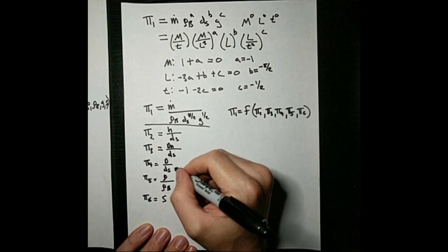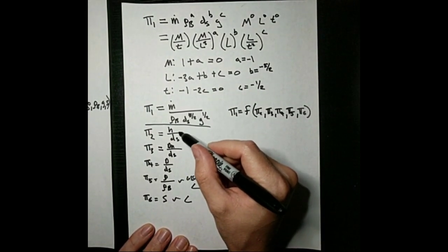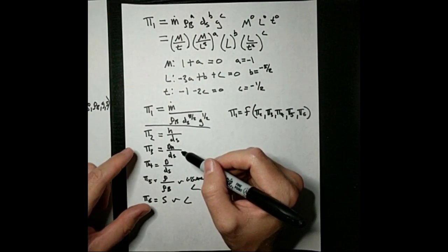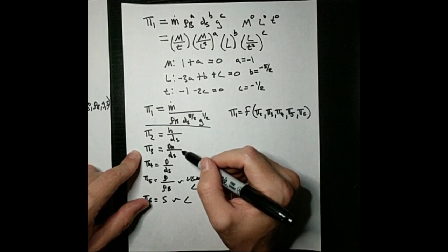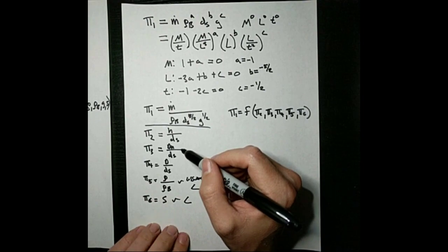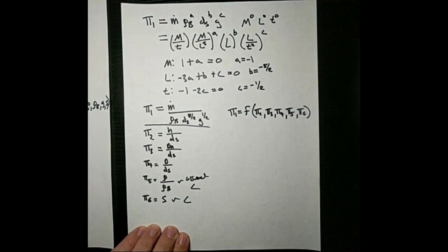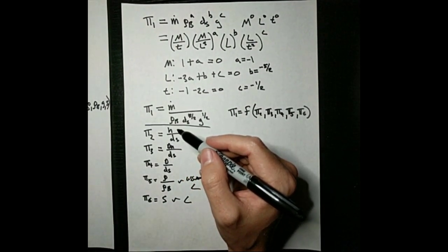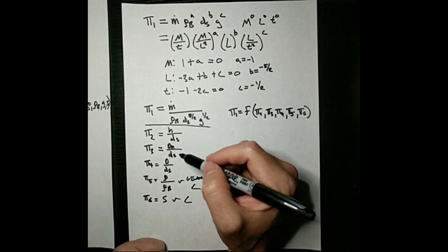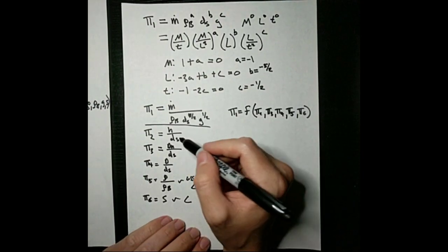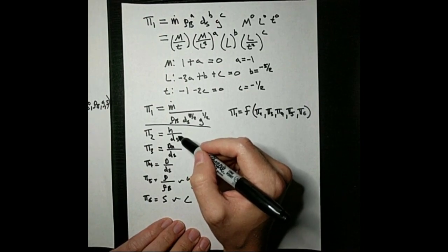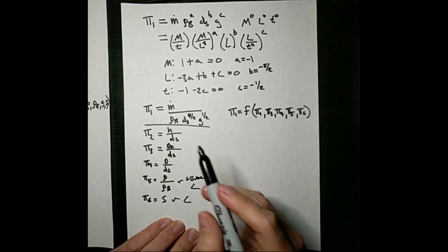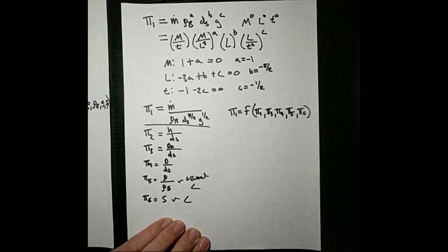And then of these, it's probably most likely that the height that we pack the material into and the size of the orifice that the particles flow out of are going to be more important than the diameter of the column, because the packing height will add pressure to the particles flowing out of the bottom, just like it would for increasing the height of a water column, and allowing a larger orifice for it to flow out of will provide less resistance for those particles to flow out of the column.